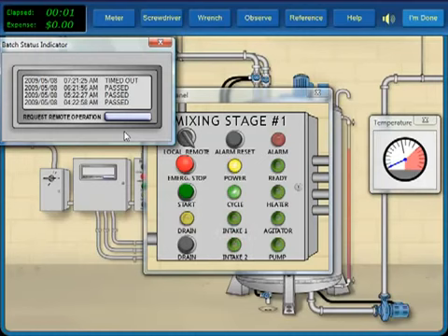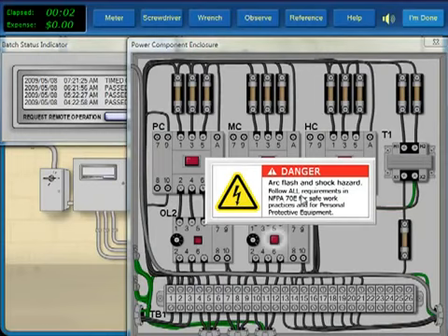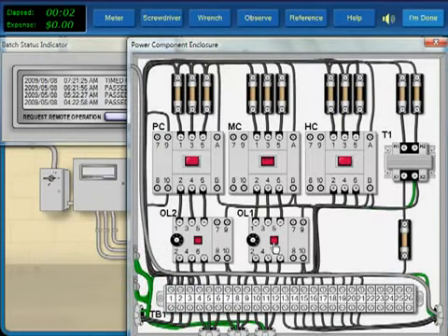At this point, the agitator light should turn on, but it does not, and we do not hear the agitator start. Inside the power box, we see that the agitator's overload is tripped. Resetting the overload causes the agitator contactor to pick up, but the overload trips again after a few seconds. To sum up our observations, we saw that the cycle operates normally up until the point when the agitator should operate, at which time its overload trips.